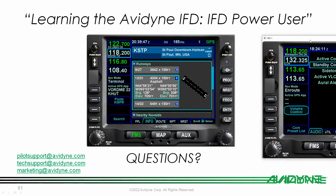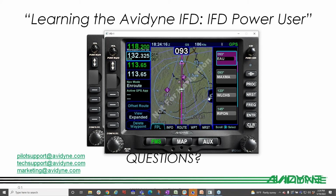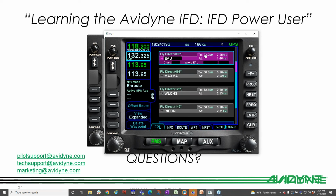I would say because it's based off of your down path waypoint, if we have an altitude constraint set, we can see that. We should be able to see that here. So look in there. If this doesn't answer his question, then shoot us an email and we can explore that further. But essentially, let's say if I had an altitude constraint at EAU and if I wanted to cross it at 5,000 feet, I'm still going to be 22 miles and 7 minutes from there. I think that may answer the question, but if not, just shoot us an email. We can explore that a little bit further.